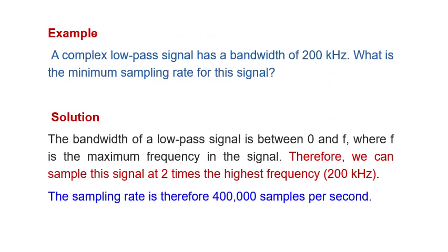First, let's look at a very simple example. After that, we will go to the sampling method or sampling technique. This question says if the frequency of the analog signal is 200 Hz, what is the minimum possible frequency to sample it? It's 400 Hz. That's it. It's just two times that. But if I give you choices, keep this in your mind. I want to sample this signal with a sampling frequency of 100